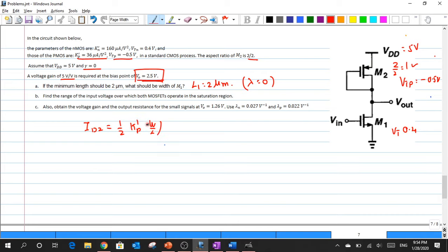So what I have really is this particular expression, and now we have to use some sort of GM such that we can connect to the W by L factor of this M1 transistor, which is what has been asked over here. As I stated before, if I go for the 2ID by VOV form, I might not be able to get the value of this W by L factor.